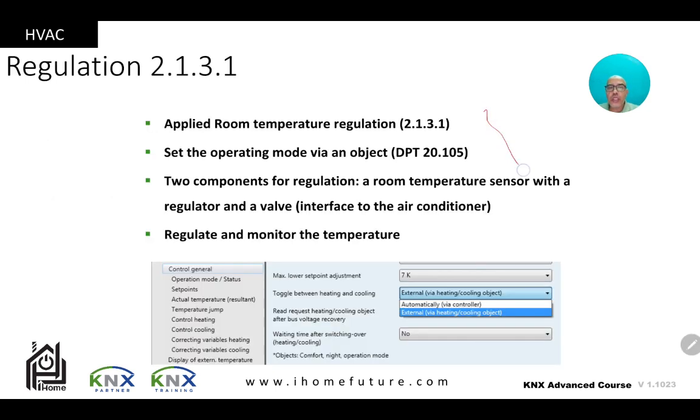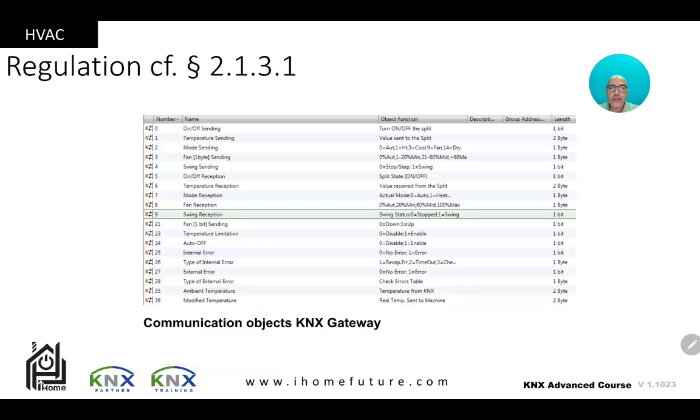Then it talks about some regulation, what kind of data point type I will have. It says that you will have a data point type for each thing in the AC. Here are the group objects you will be using, and we will cover this in the practical part, inshallah. For each property in the fan coil unit, you have a group object, and these group objects in the actuator should also be found in the screen, the LCD or the thermostat. When you connect both together, you get the desired data that you need. Here is the control via the KNX gateway.